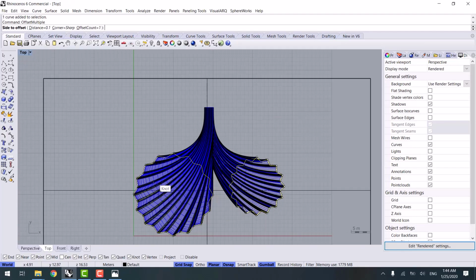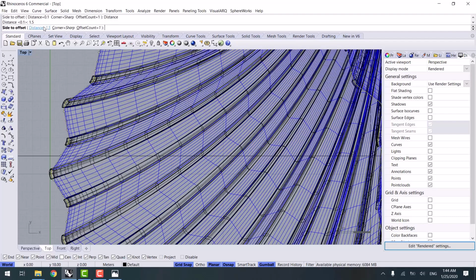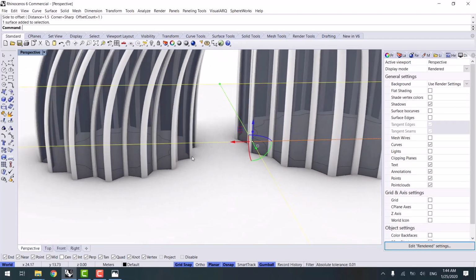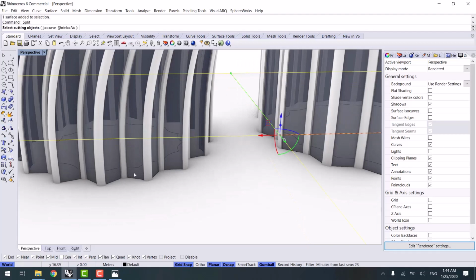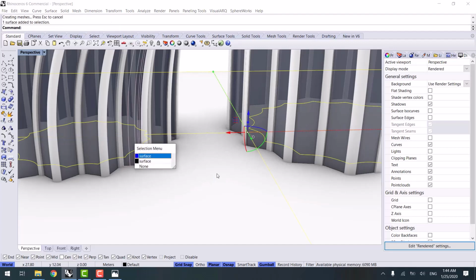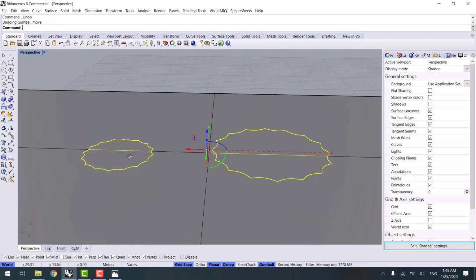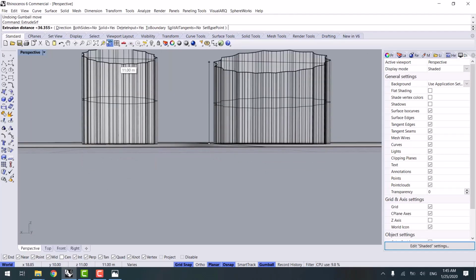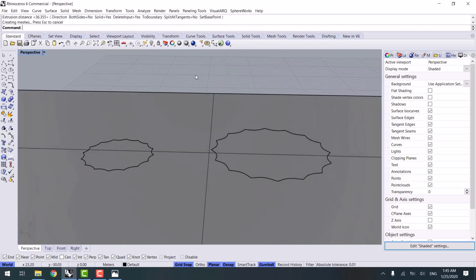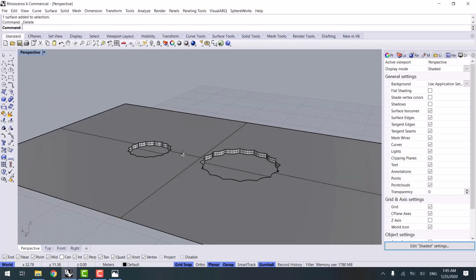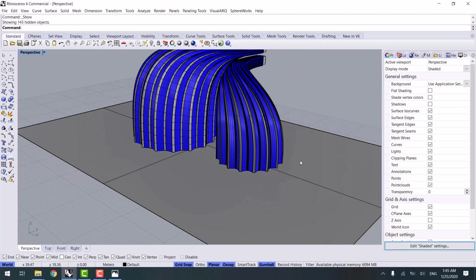Okay, as many as 1, and the measure could be 1.5. I made an offset, and I split the bases beneath my work using these two lines. The surface, select command and then isolate, and then we use extrude surface. Solid must be on, yes. I press Ctrl Shift these two and I delete them, and then I unhide the previous objects.